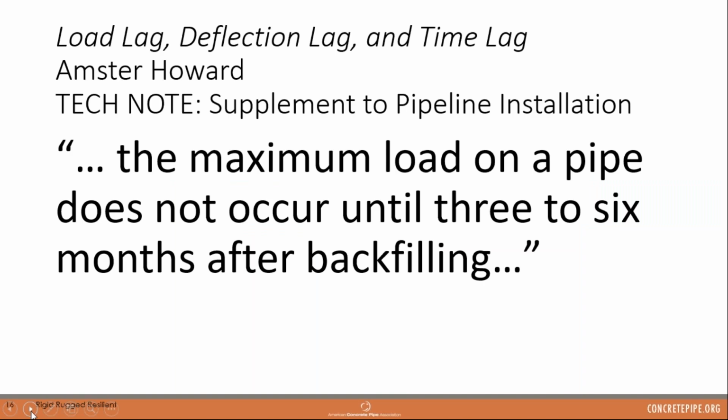Awesome. Okay, so another quick note on that is a note from Amster Howard's work on load lag, deflection lag, and time lag, an article specifically related to flexible pipe. Amster Howard is a technical expert on the subject. He spent about 30 years with the Bureau of Reclamation, and he's written several books and technical papers on these types of subjects. In a technical note, he states that the maximum load on a given pipe doesn't occur until 3 to 6 months after backfilling. So even with that 30-day waiting period, you might not be seeing the most load that pipe experiences.